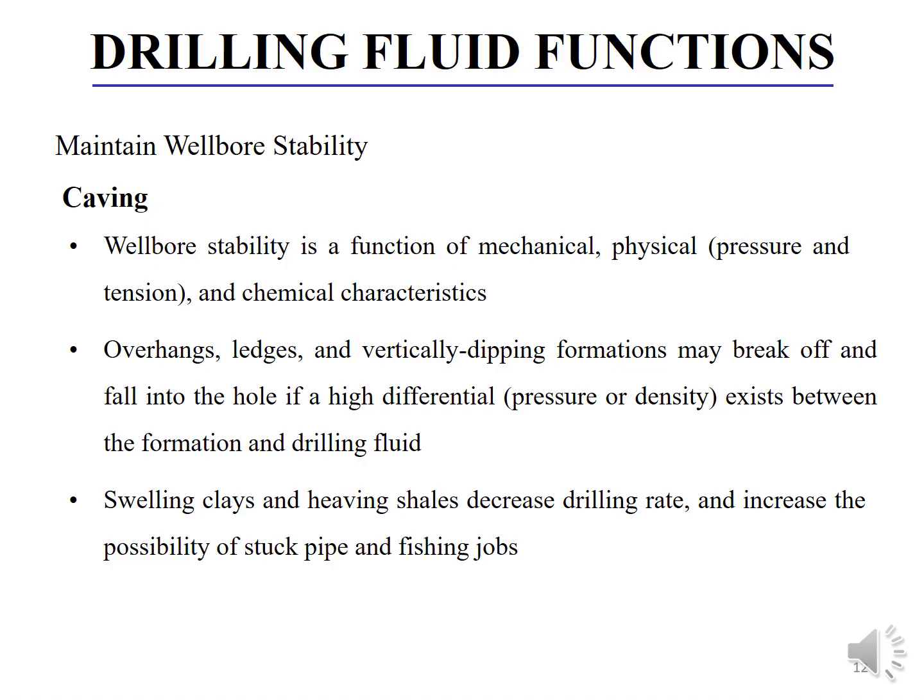First property is caving. So wellbore stability is a function of mechanical, physical and chemical characteristics. Overhangs, ledges and vertically dipping formations may break off and fall into the hole if a high differential exists between the formation and the drilling fluid, in terms of pressure or density. So swelling clays and heaving shales decrease drilling rate and increase the possibility of stuck pipe and fishing jobs.